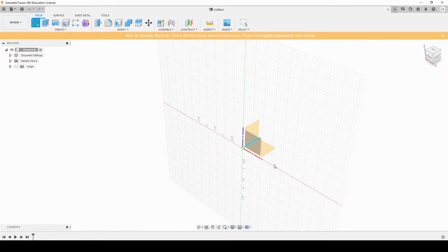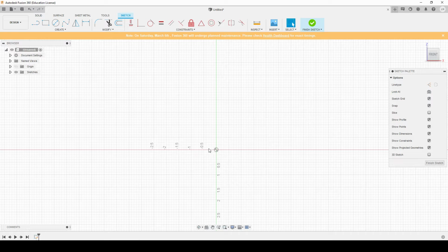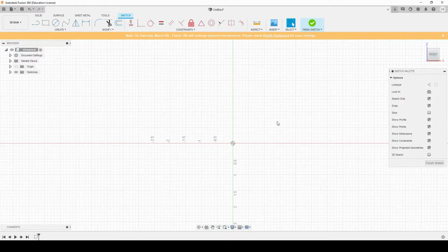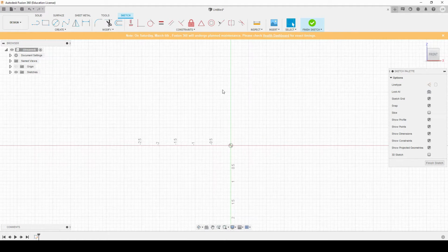Once you click create a sketch, it's gonna ask you to click a plane that you want to draw the sketch on. 3D space, as you may have figured, is in 3 different planes. So just pick one. I'm gonna pick this one right here. Once you pick that plane, it brings you onto a working drawing workspace. It's got a grid with different values of dimensions and all that. One rule of thumb is to always draw all your shapes centered right down here. It makes your life a lot easier later on when you're trying to do mirrors and more complicated things in the future.